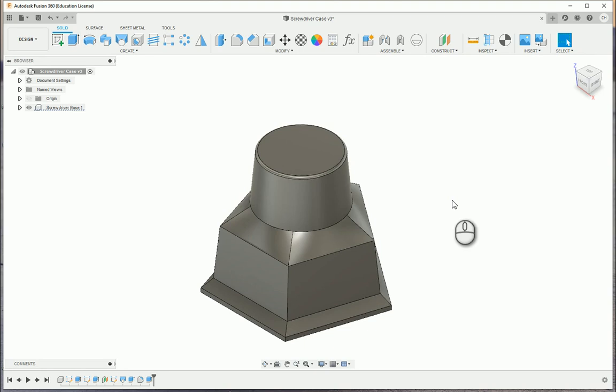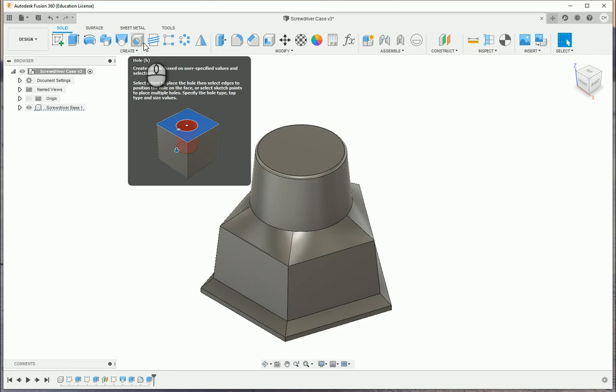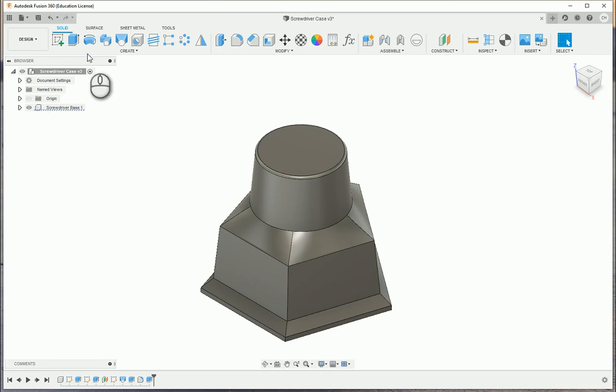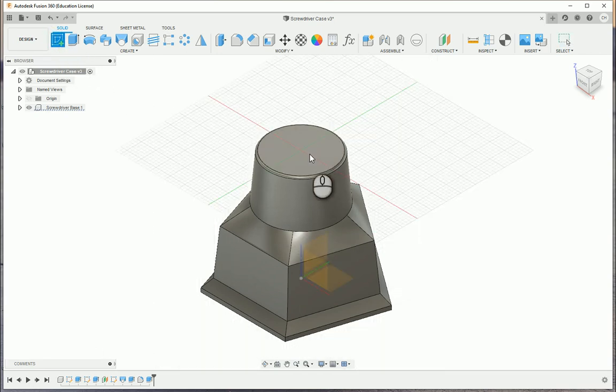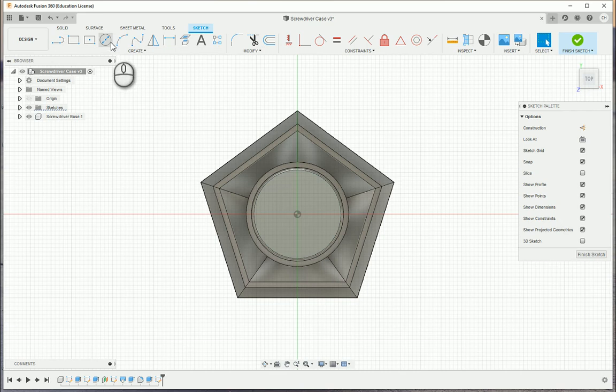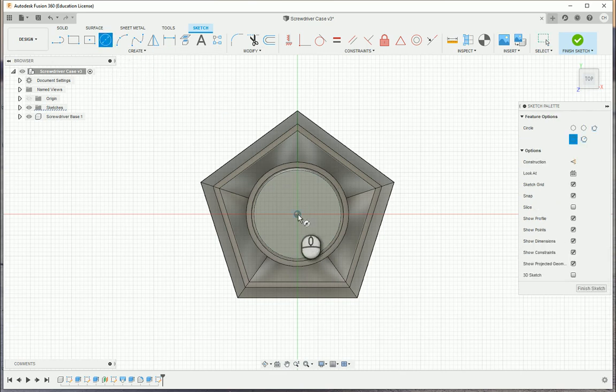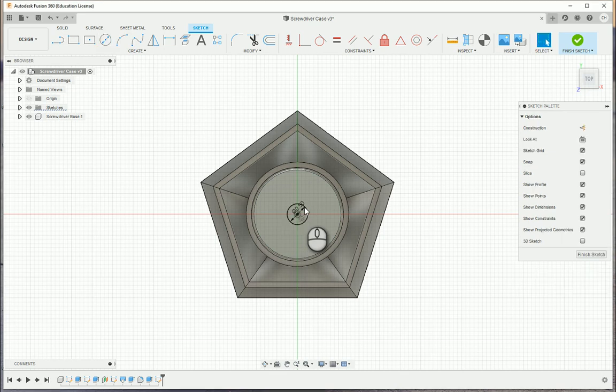As we go along, step 22, we're going to model the center hole in the top. One of the notes on the activity is we don't want to use the Hole command. Typically, I try to use the Hole command anytime I'm creating holes, but because of the taper that can be put on this, they recommend creating a circle. So I'm going to create a new sketch and select the top face. I'm going to choose a center point diameter circle, choose right on the origin, and make this, since some of the dimensions I've used, 1/2 inch.